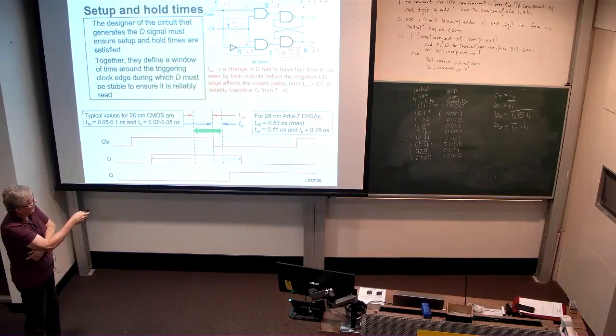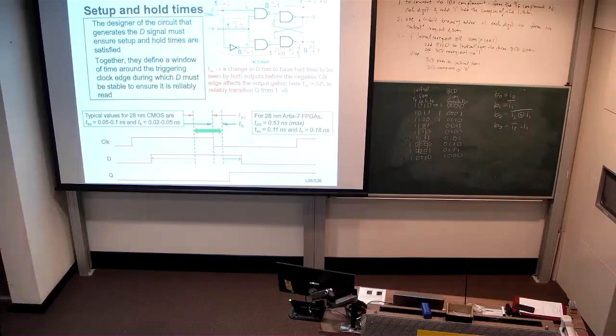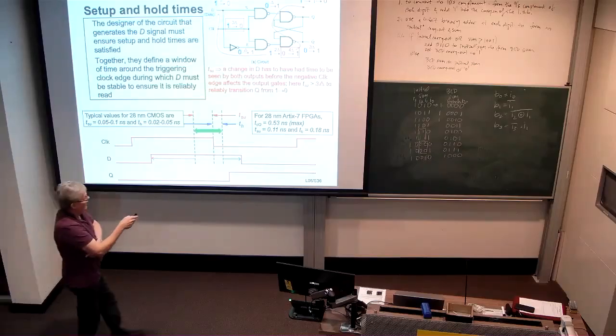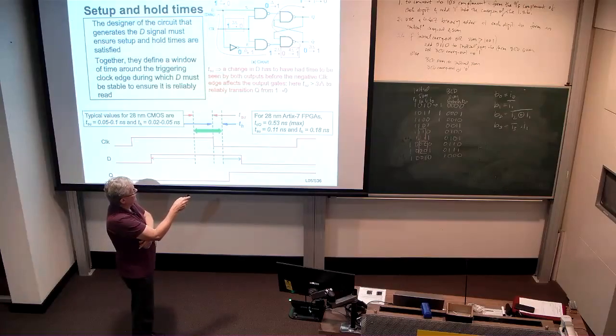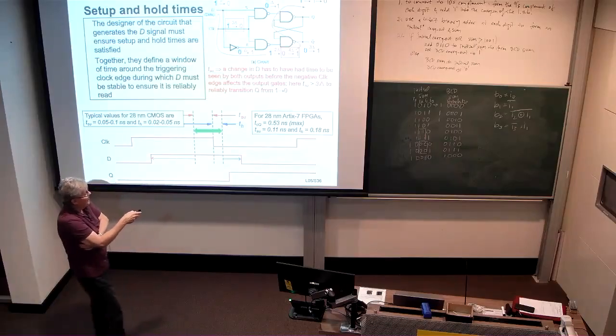After 3 delta, we get a 0 input on this NAND gate. As a consequence, this NAND gate has to go to 1 at 4 delta time, right? But at 4 delta time, that's the time that this guy has just gone to 0. So now we have the 0 coming in here and the 1 coming in here, and therefore the output here is going to go to 1.